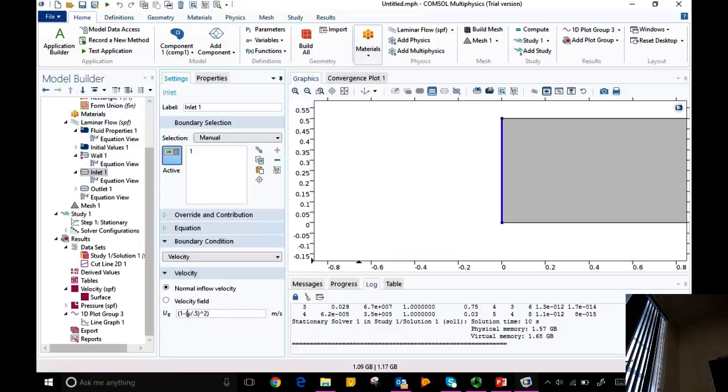So what I want you to do is put a parabolic profile that I will get as the solution for this. If it is a parabolic profile, it's going to be something like a plus by plus cy squared. So I need to find a, b, and c in such a way that it gives the parabolic profile. Now b has to be 0 because it's symmetric, right?